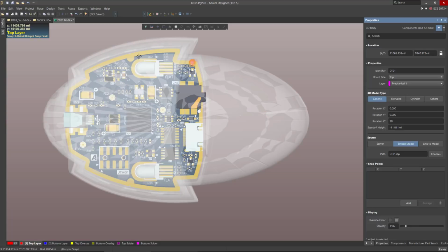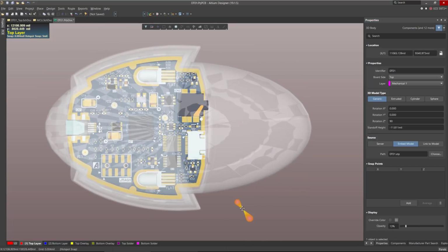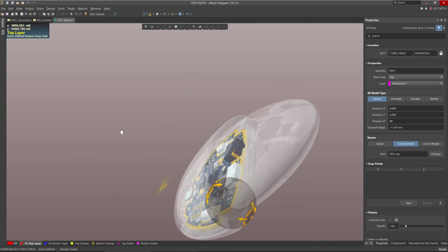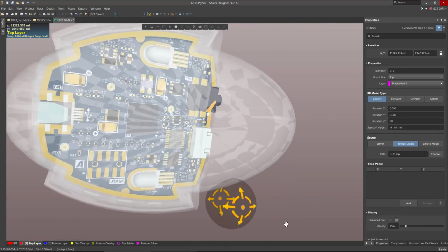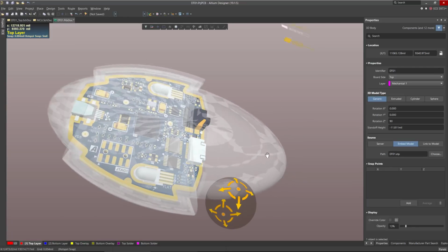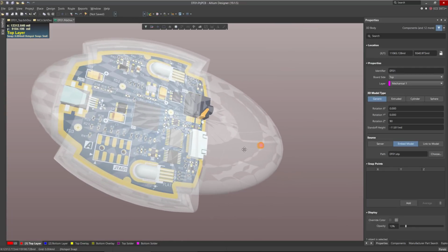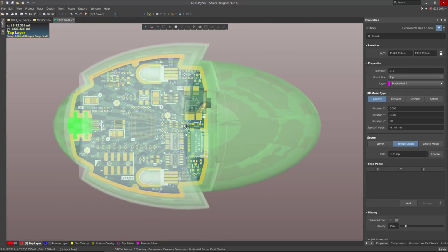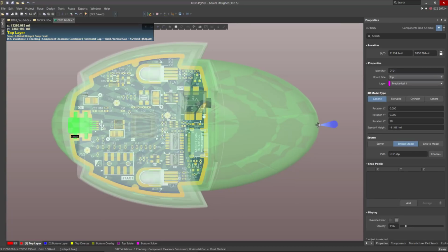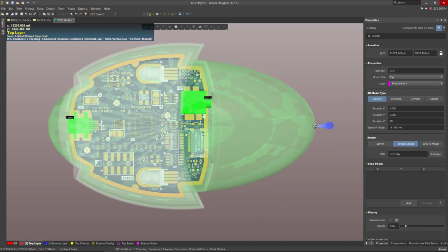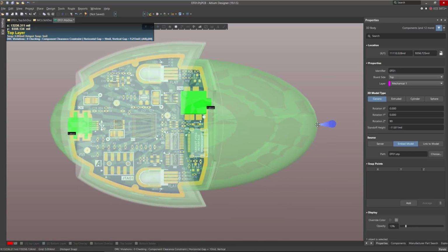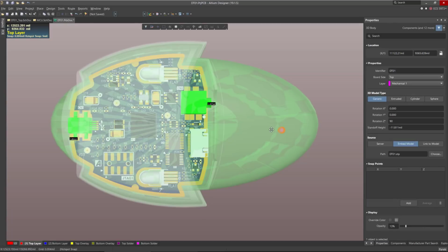And the reason for that is, now you import this mechanical design from the MCAD engineer, and you try to do a clearance check. Make sure that everything will fit together and there is no problem with the clearance. And for instance, let's try to move this a little bit. You see there is a collision in here, there is a collision in here, and you try to fit that and see if there is any collision. You send it back to the mechanical engineer and explain.